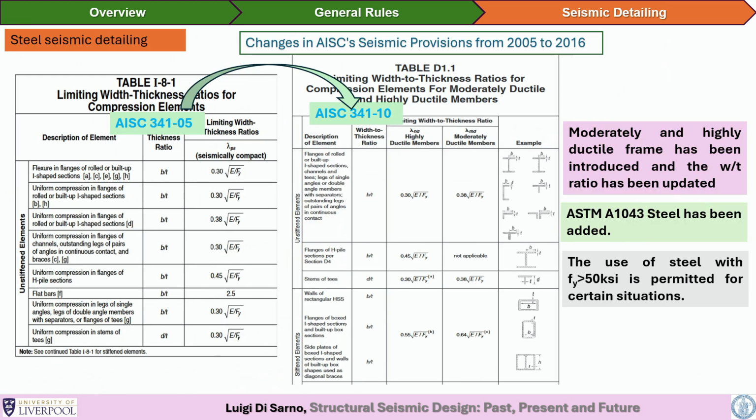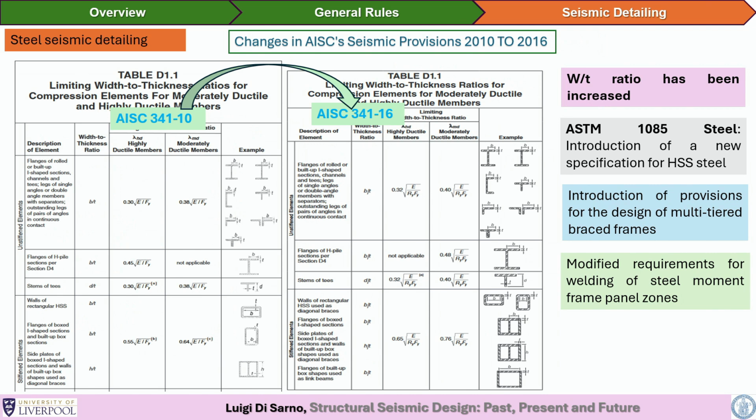So these are requirements for steel. It's exactly the same because of the thickness, so the slenderness of the components is becoming smaller and smaller. So it means that the system needs to become more robust. So it means that we are going to act on local b over t, which are local reinforcements, or in this case, local buckling to be prevented. And this has been implemented in recent practice, for example, since 2016 in AISC, American Institute of Steel Construction.